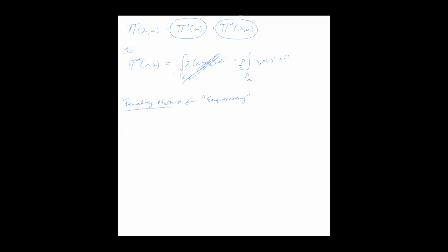It's force times distance squared, and then we integrate, which will get rid of one of the distances. So this is like a force times a distance. What is this penalty term basically a model for? Force for overclosure? It's just a spring.